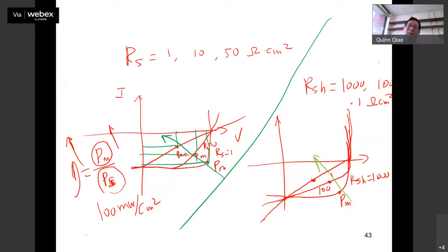And the other thing would be how to prevent ion diffusion, or ion migration inside the device, especially when the temperature is pretty high. It's not that high, maybe 80 to 100 degrees under sunlight, especially in hot areas, but then the ions probably diffuse and migrate. How can we hold these ions there so that they cannot diffuse? Then the ions will not migrate. You will have a very stable morphological phase, and also a very stable chemical phase inside the devices, and the device should work for a long lifetime. So that's what I thought.